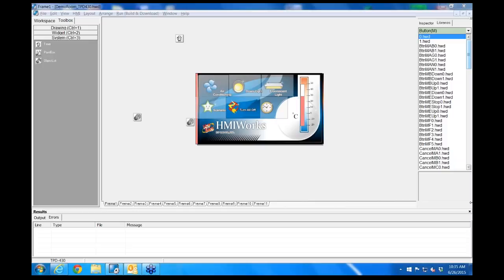It can learn up to 176 different IR commands, and you can program them into the IR210. Then you can program the touchpad controllers so that, with the push of a button, you can control your television, projector, or any other kind of infrared equipment. The IR210 is a Modbus slave device.